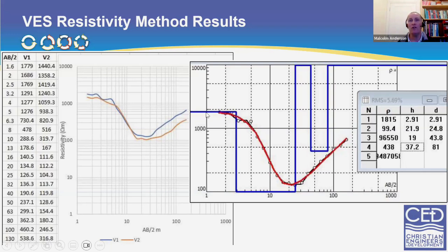Now, when you have no water in soils, obviously the resistivity is much higher. So what that's really telling you is that you've got a water level that's around about 3 meters, and then you've got a weathered layer with no clay, because clay would have a much lower resistivity, and that takes you down to 25 meters. And then you've got a transition from this soil horizon or weathered rock horizon up to the more consolidated rock around about 80 meters.